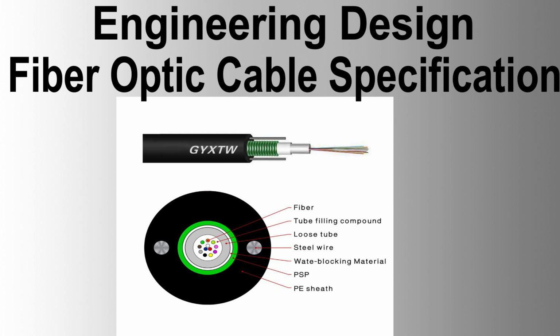If connectors exist in the cable under test, then 2 traces shall be recorded. 1 trace for the fiber loss, dB, an average attenuation, dB per kilometer, of the entire cable segment, including connectors. The second trace for a magnified view of the connector regions, revealing connector losses, dB.